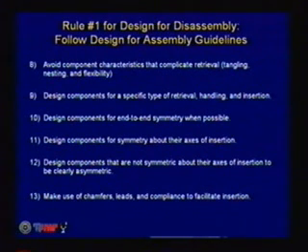Design for the use of retrievable materials, end-to-end symmetry, right? Like your car keys. As much symmetry as you can get, so it doesn't matter how you assemble it or how you disassemble it. If you have an asymmetry in your assembly, make sure it's plainly obvious. Suppose your car keys only went in one way, but you couldn't really tell which way they were supposed to go. Then it gets really difficult to start your car. So make it obvious, like this way is up.